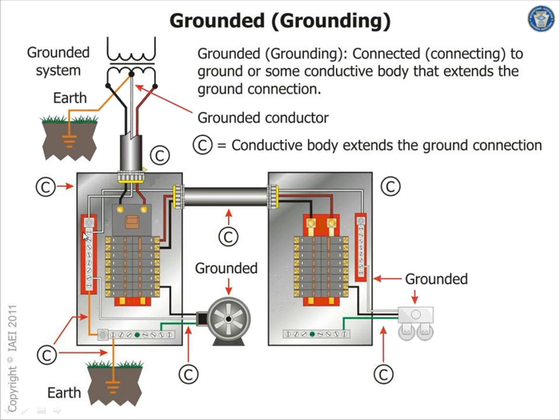Yes. Now we're coming to this one. First we grounded the system, which we're doing right in here. Then we grounded the equipment, which is all the panels, the transformers, the frames of these air handling units, as well as the fans. Then only at the service, you bring grounding the system and grounding the equipment together by bonding them together. That's what they call the main bonding jumper.